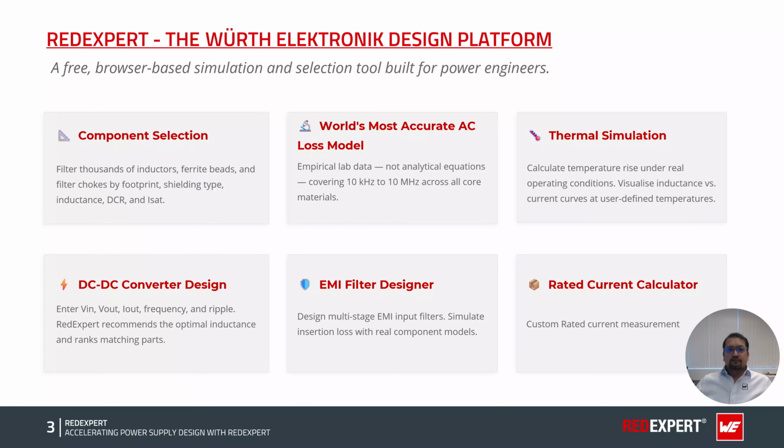REDEXPERT is a Würth Elektronik free browser-based design platform built specifically for power engineers. No installation, no license fees, just open your browser and start designing. At its core, REDEXPERT does several things. First is component selection. You can filter through thousands of inductors, ferrite beads, filter chokes, and common mode chokes, based on footprints, shielding types, inductance, DCR, and saturation current instantly.